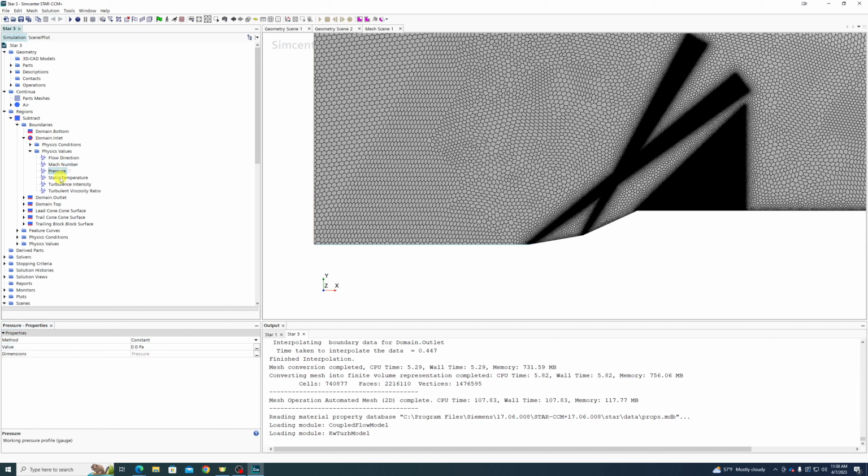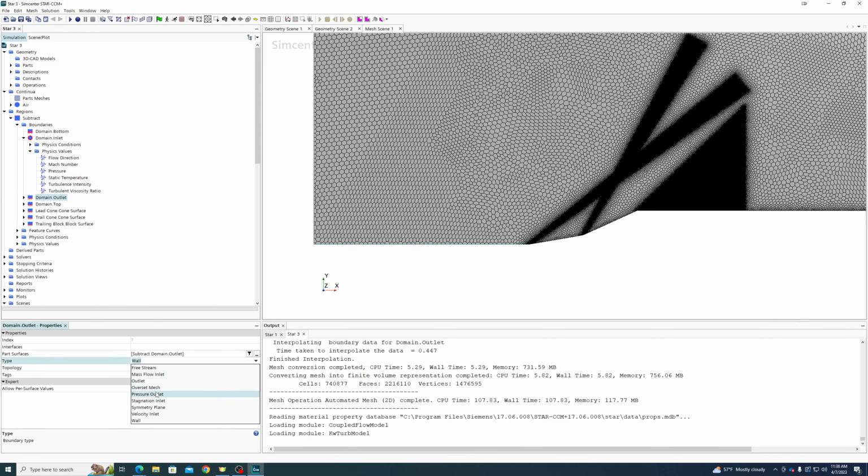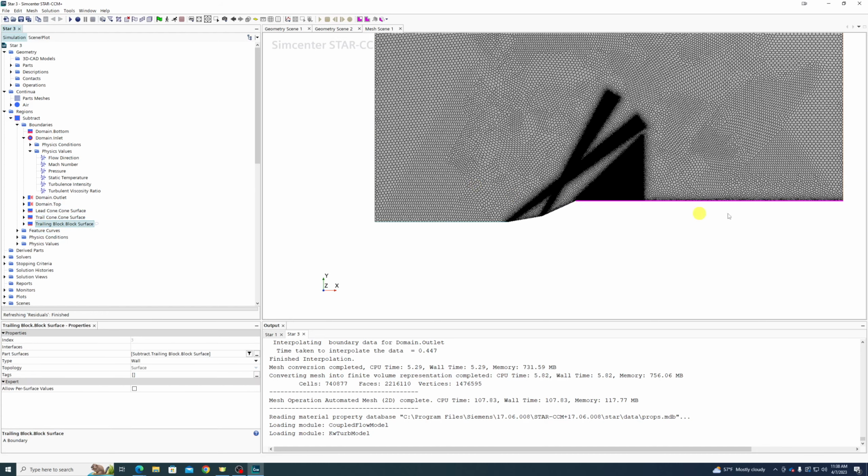We're going to set it as Mach 2. 300 Kelvin, sure, that's reasonable enough. Pressure outlet on the back. We're going to also have a pressure outlet on the top. These are all walls. That is fine. So effectively, we're looking at like the leading edge of like a shock tube or some sharp edge thing with some sharp edge ramp.